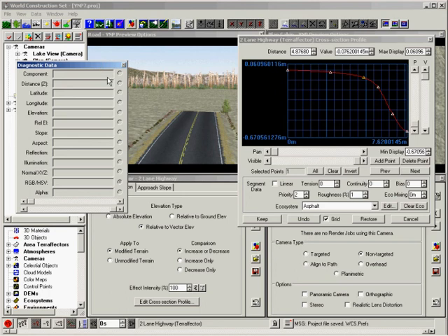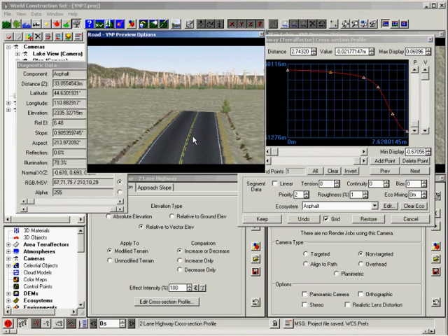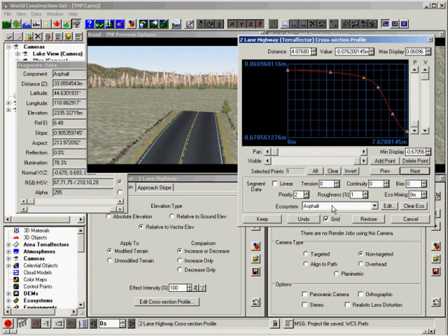The center line of the road starts at the vector elevation at 0 meters. It has the asphalt ecosystem attached to render left of the point. The next point is about 2.7 meters away from the center line and slightly lower. It also has the asphalt ecosystem, so it renders asphalt between this point and the first point. The third point also renders asphalt to the second point.